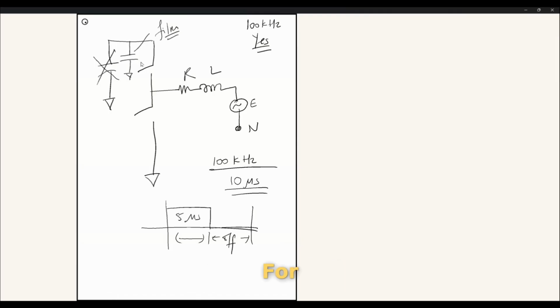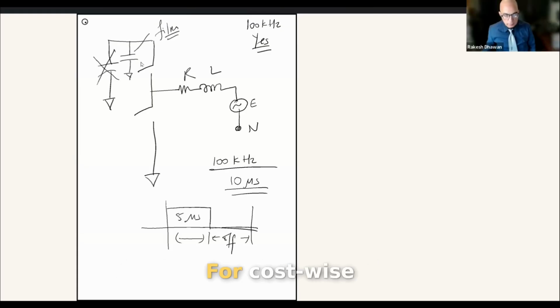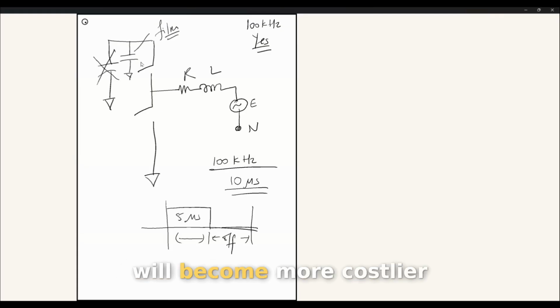Is that possible? I think for low power drive it is possible. Okay, and for high power drives? Cost wise, I guess film capacitor will become costlier. But if we consider reliability over cost, then we can go for it. Okay,